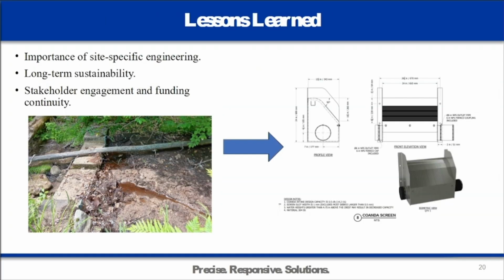A couple things to note when looking to do this type of restoration. You're not limited to the location that you're placing this system. With an AMD system, you usually have a discharge there, and you have to center your system around that discharge or pipe that discharge to where you're looking to design that system. Well, with this, anywhere on the stream in the headwaters, you can place that system, as long as it meets the site constraints of a fairly flat site, fairly easy access to the stream. You're able to put these types of systems in.